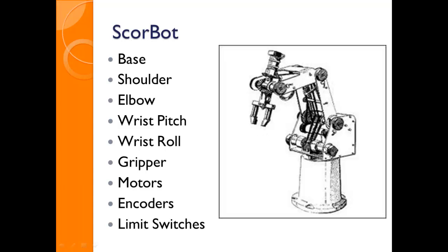And there are motors. Here's a motor, here's one, there's some inside here, there's a motor, here's one, there's some there, okay? And the motors are controlled by encoders in these boxes on top here, here, here. Those are optical encoders, and they're also limit switches. You can see right there, that's a tiny little limit switch. There's a cam on this dial that when it rolls into a certain position, it'll make contact with that very tiny limit switch.